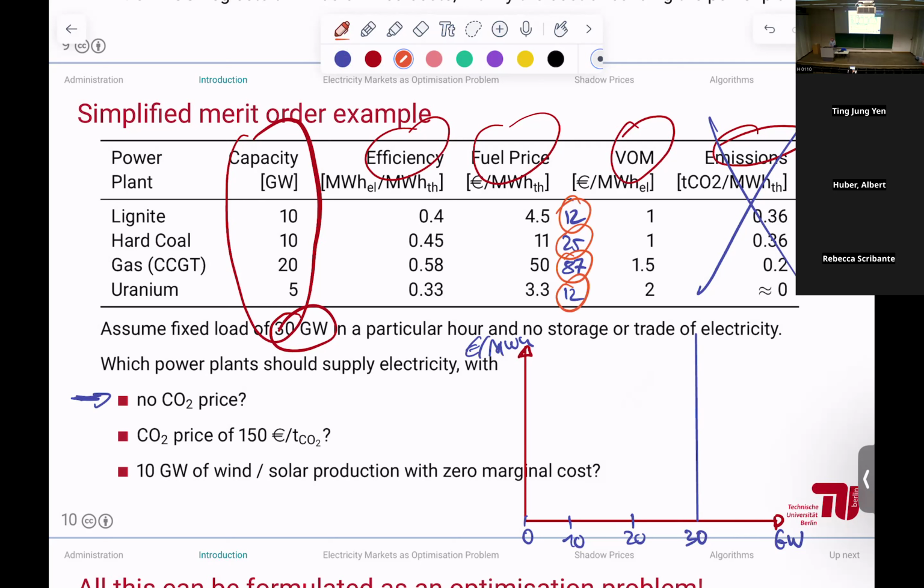So what we need to construct the merit order is basically these short-term marginal generation costs of the different fuel types and the available capacity. And now we go from the cheapest to the most expensive one. I think this one was on position 1. This one is in fact slightly higher if I consider the decimal points. And then we have at the third position this one, the fourth position this one. We have 5 gigawatts of the nuclear.